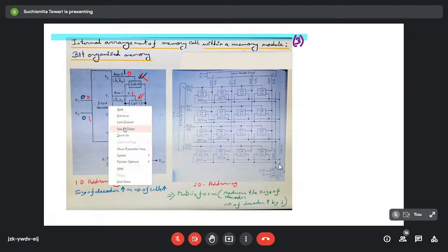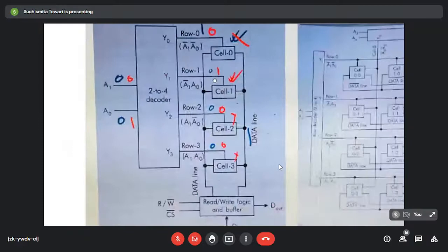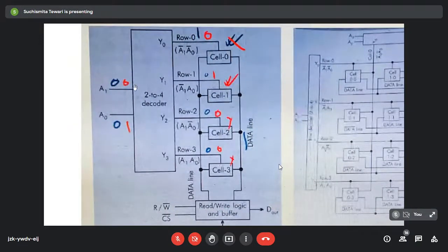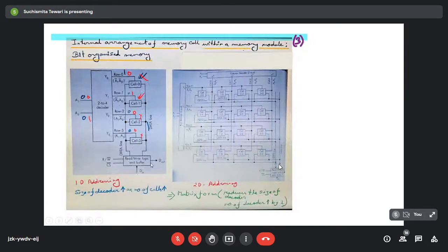First, let us focus on this particular design. We have used a decoder. Suppose we have got 4 memory locations, and the output would be 1 bit in length. That is, when one particular cell is pointed to or selected, from the output of that cell we can get the output of that entire system. So basically this is a bit oriented memory, each cell containing 1 bit.